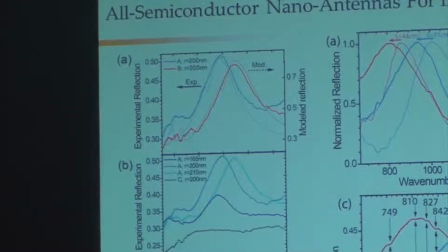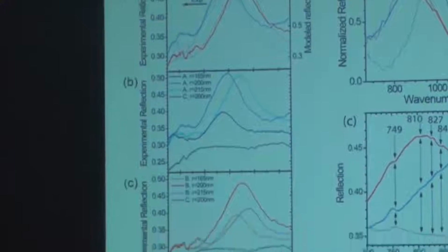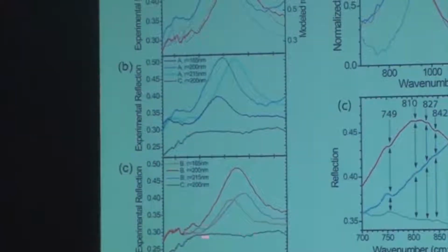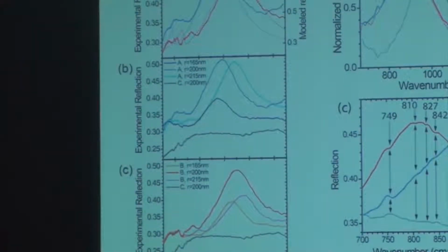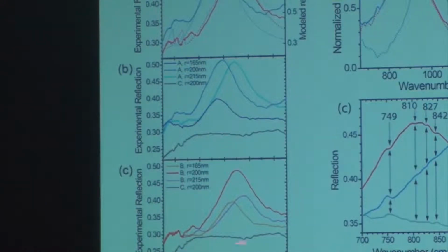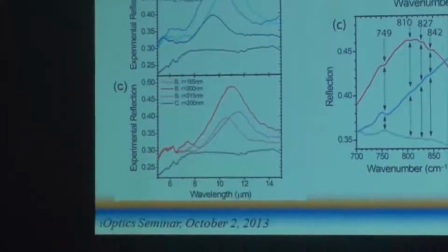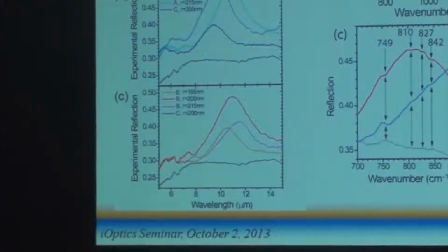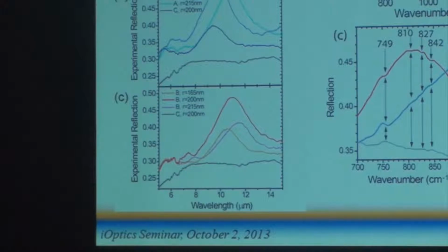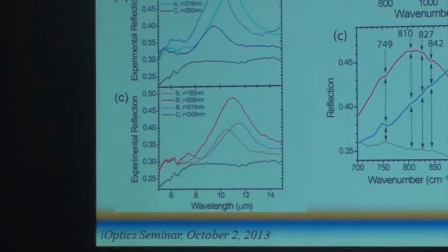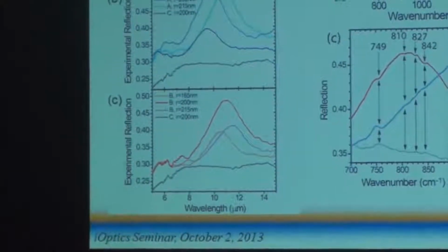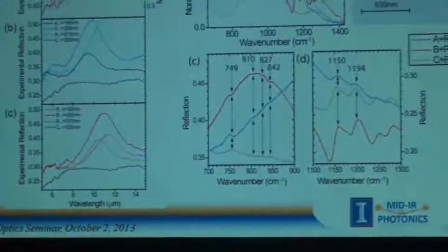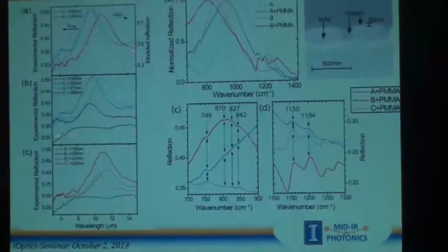Okay? And so if we compare any set of antennas in the two different material systems to an undoped sample that has been fabricated in the exact same way, so the same geometry structures, you can see that, again, this behaves exactly as you'd expect a semiconductor surface to behave. 30% reflectivity, no reflection peaks or any sort of resonances that can be observed. Right? But when you use the doped surface, when you make these nano antennas, you in fact see